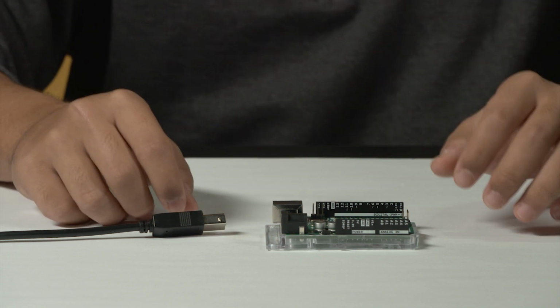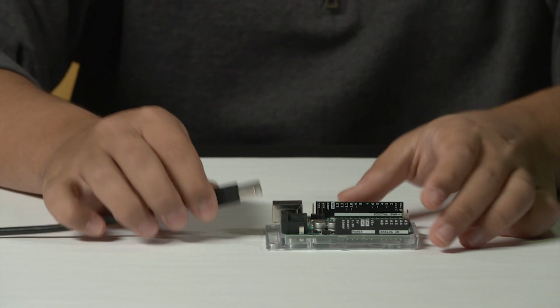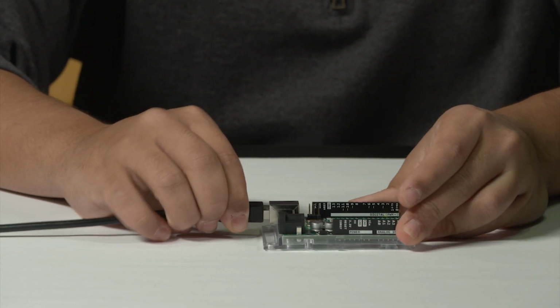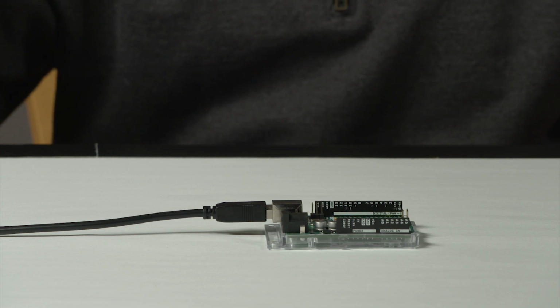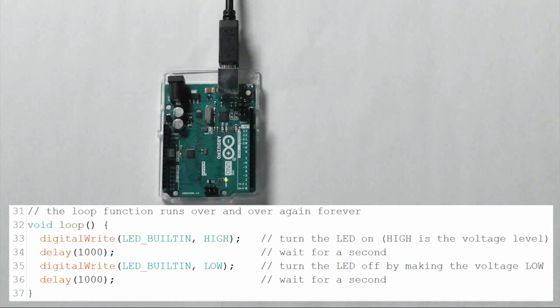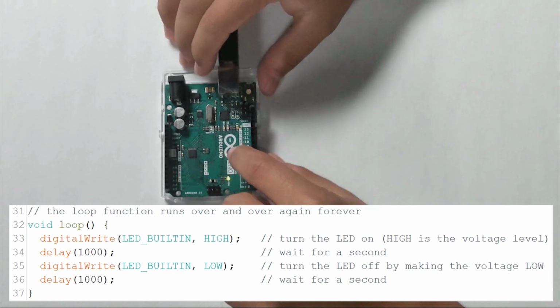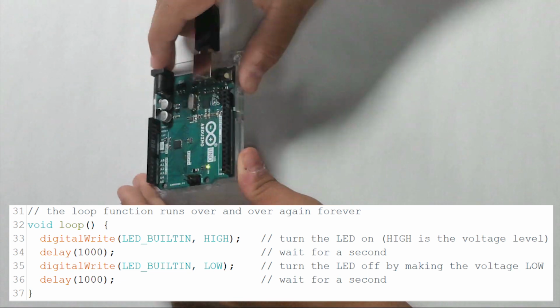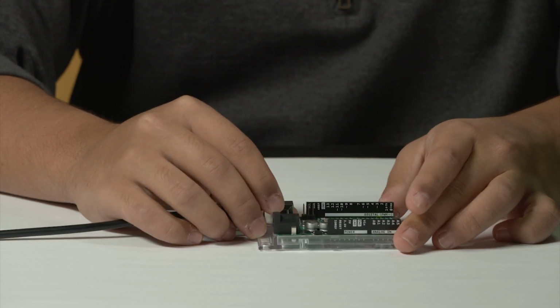Okay, so for this, all we're going to do is first connect our Arduino board to our laptop using the USB cable. Once we've done that, we want to pull up the Blink example code from the Arduino library, and we're going to hit the upload button. This is going to compile our code and send it to the Arduino, and now we can see that the small LED on the board starts to blink on and off every second.